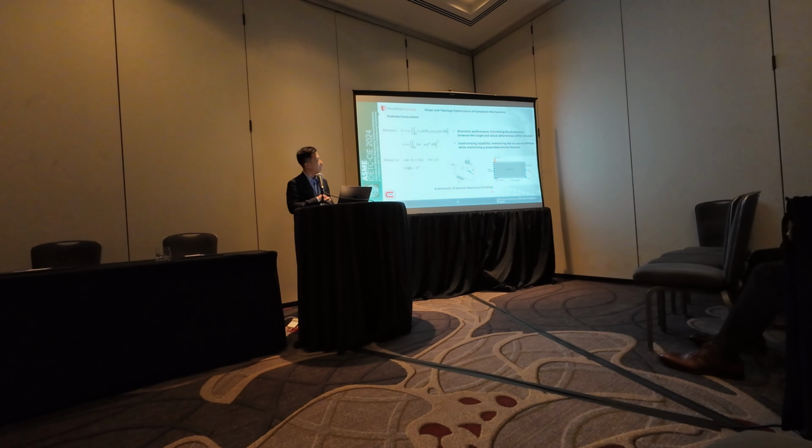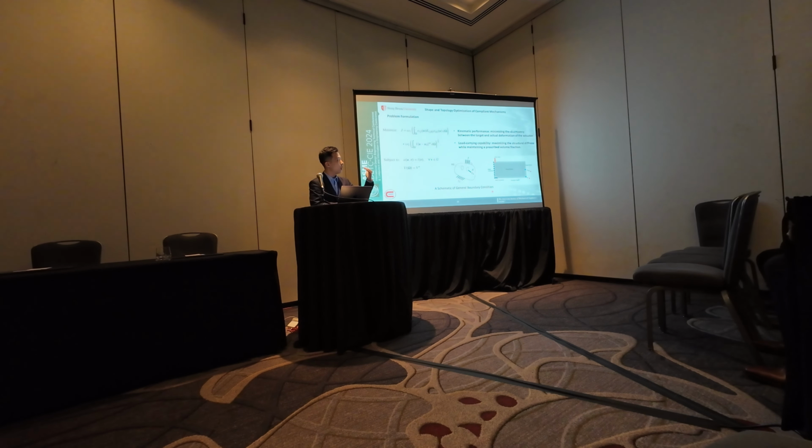Okay, so back to our problem formulation. This design problem can be formulated into two objective functions. The first one is to minimize the error between the actual displacement field and the target displacement field. The second objective function is load carrying capability, which is to maximize the overall surface stiffness, that is, minimize the compliance of the overall structure, while maintaining the prescribed volume ratio. And this design problem is subject to a(u,v) = l(v), where a(u,v) is the energy bilinear form, l(v) is the load linear form, u is our state variable, and omega is our design variable.